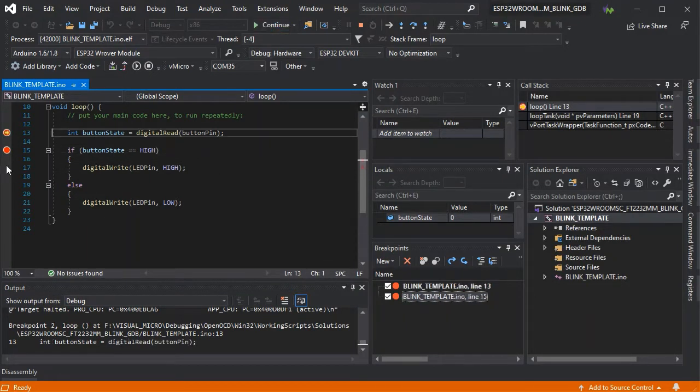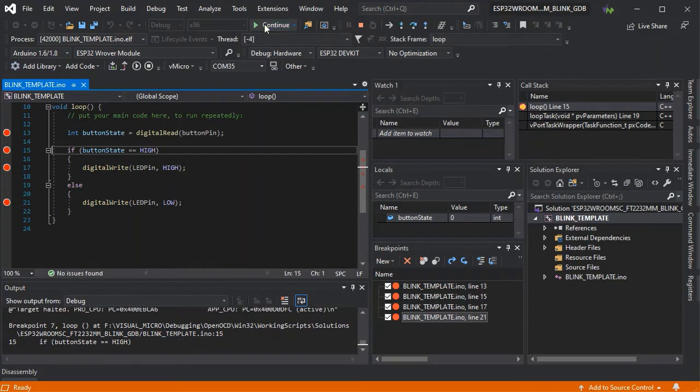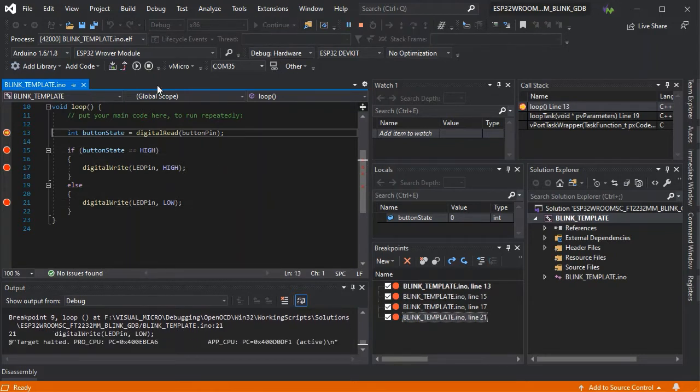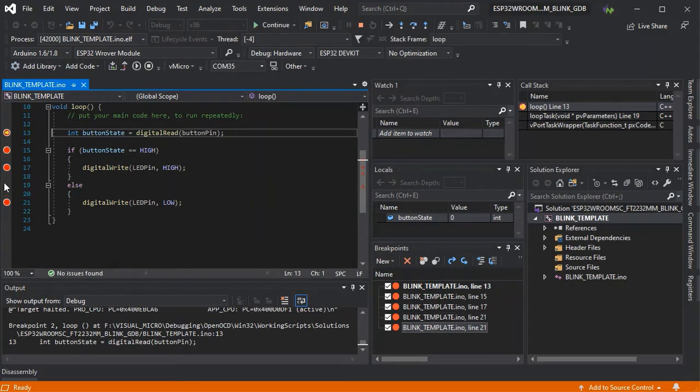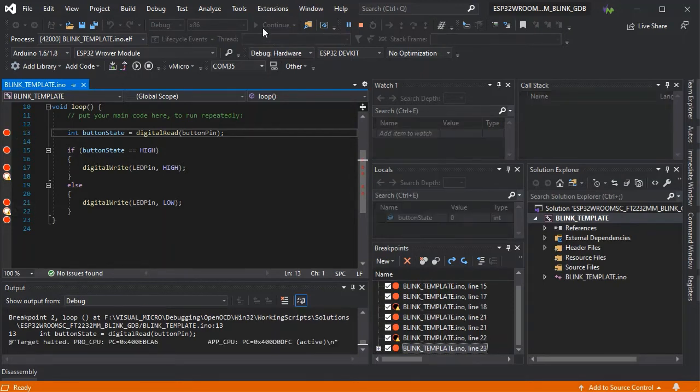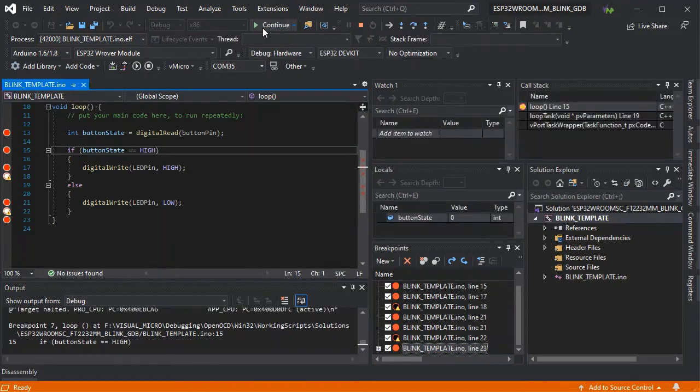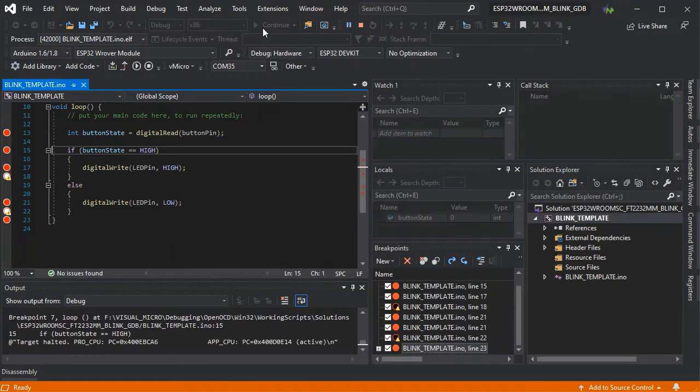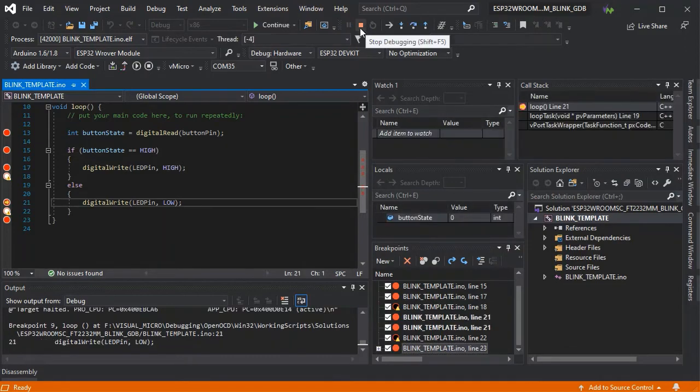Now with this particular debugger, there is a limit of 2 hardware breakpoints, and that's what these are. So as you can see now, there's a much bigger slowdown going between them. And if we try and set more, there's not really any more valid space in this example. We'll see that it becomes even slower. This is because it's having to swap the breakpoints around in the background between each one, as it only actually has 2 slots to use to track them in.